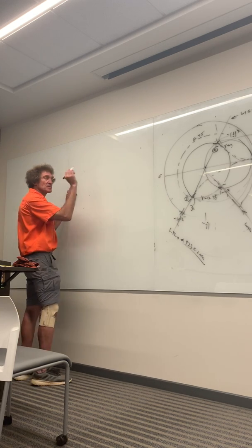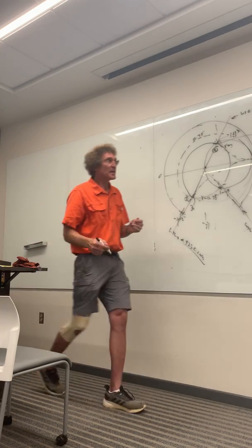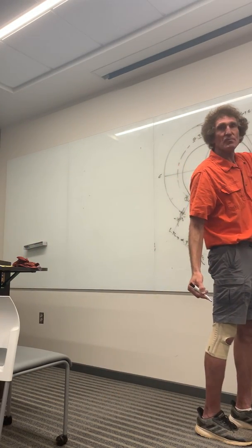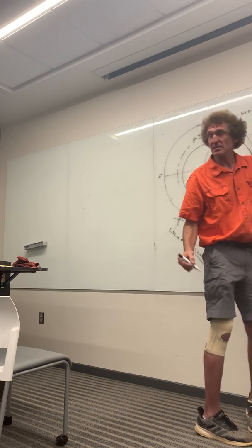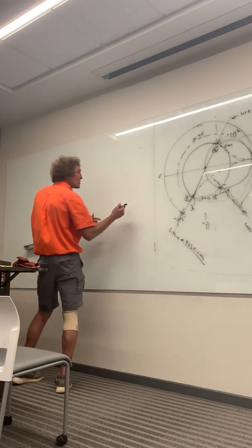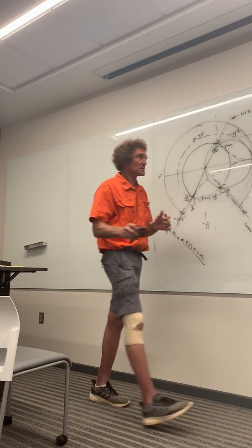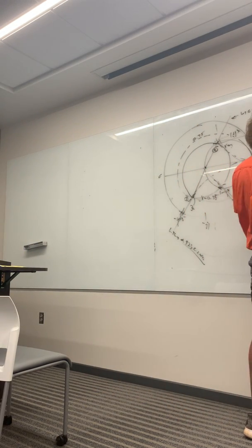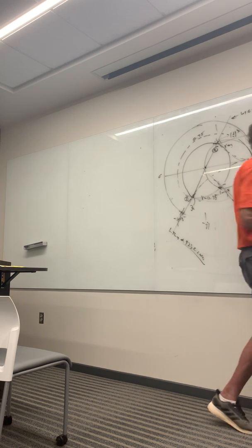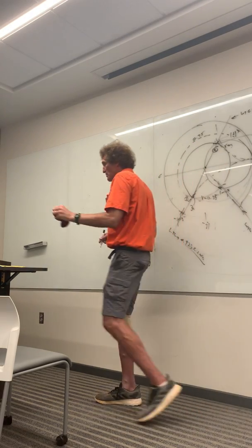So when I have a transmission line, let me show you something. Suppose we wanted to get that minus j1.4. I want you to watch this. If I want to hook a transmission line in series with this that has minus j1.4, here's my transmission line. Now I'm going to take another piece of transmission line with a short circuit, and I want this thing to have Zn right here of minus j1.4, and the characteristic impedance will be 50 ohms, or 100 ohms. It'll be the same as before. Follow me? So how do I get minus j1.4?